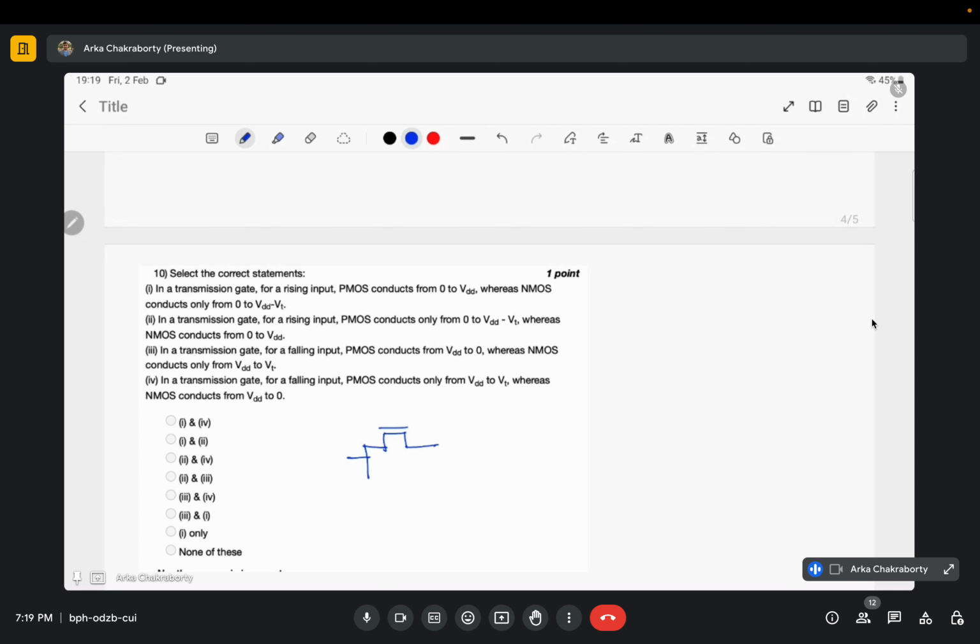Transmission gate logic is nothing but an NMOS and PMOS connected end to end in a kind of parallel fashion. Why are such switches used? Why is a transmission gate used? One reason: I know that NMOS can only pass a strong 0 but passes a weak 1, a degraded VDD.